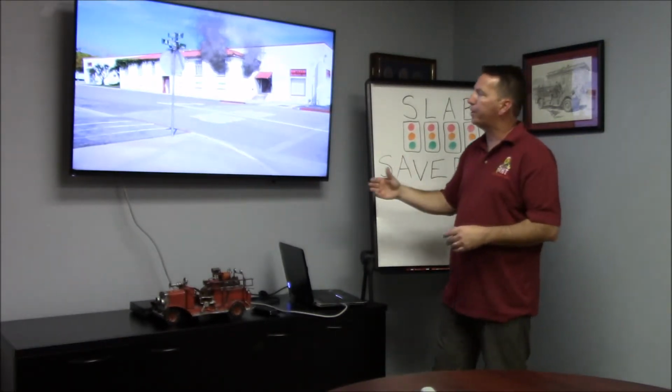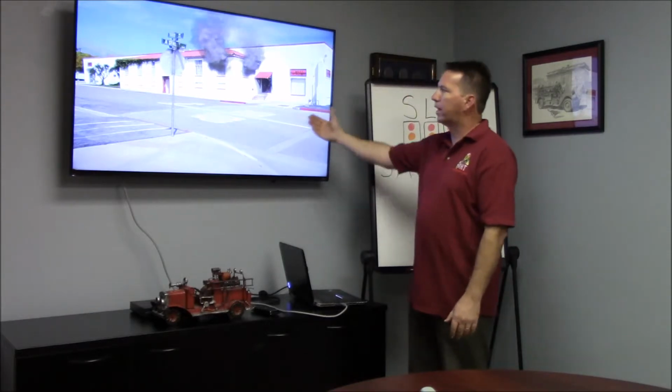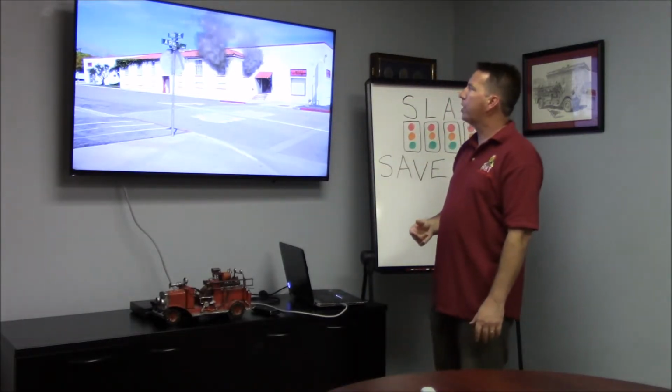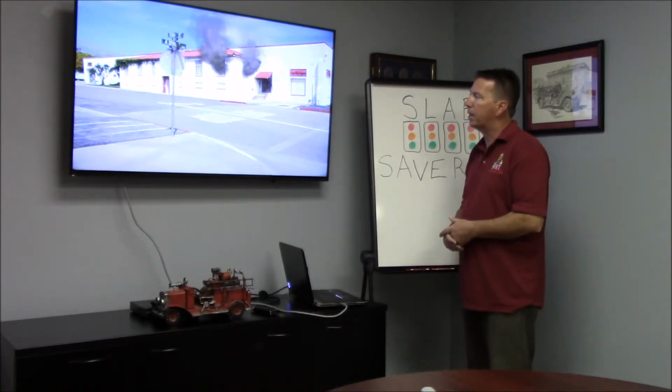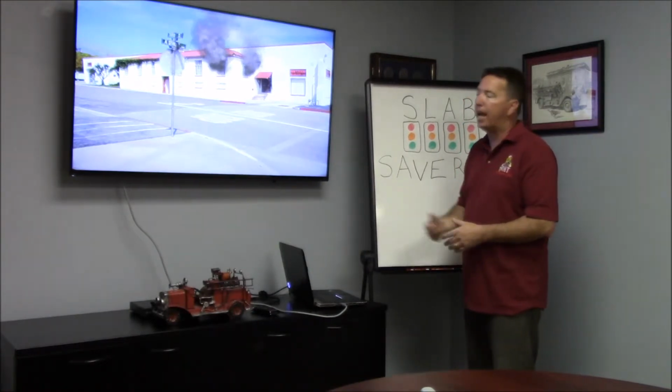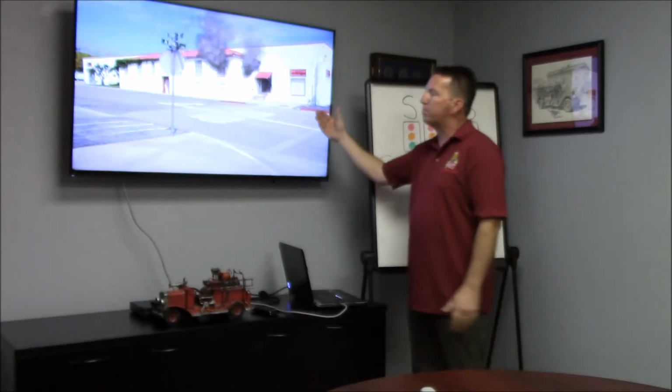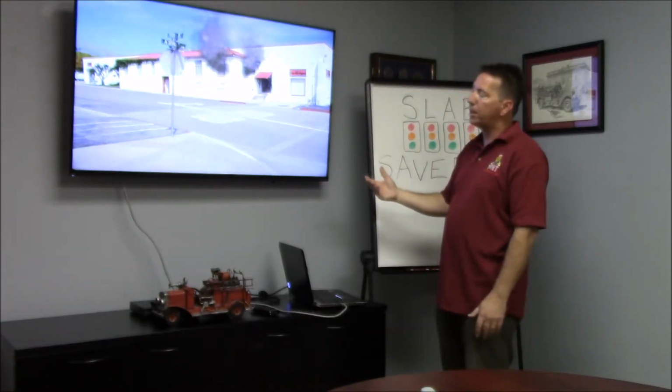And then your building profile. We've talked about a couple different things as far as it's multi-story and it looks like it's big box in the back. But other things that are going to come into play on this: is it sprinklered? That's going to be a component we're going to look at. How are you making access? And then looking at actually how this building is built. This building is actually kind of tricky.